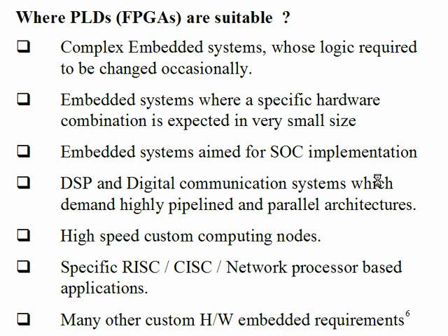But apart from that, today's modern FPGAs come with a variety of features. They come with RAM inside. An FPGA will come with block RAMs. We will see in Spartan 3 that block RAMs are there. FPGAs internally also come with high-speed multipliers. They will have 18 by 18 multipliers in them. Some FPGAs will have 50 multipliers, some will have 200 multipliers. Those multipliers can be used whenever you want to do high-speed multiplication.